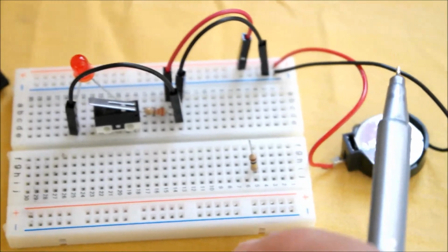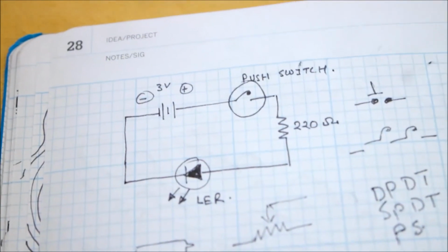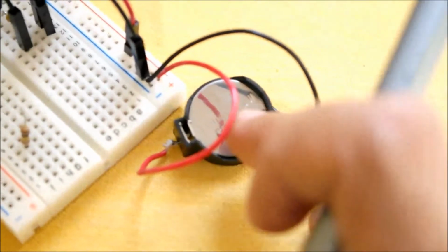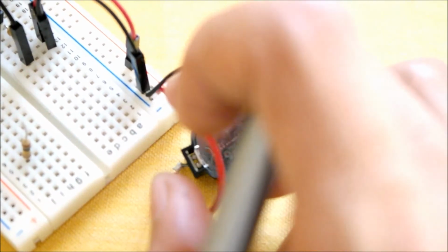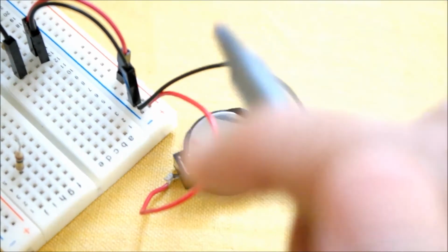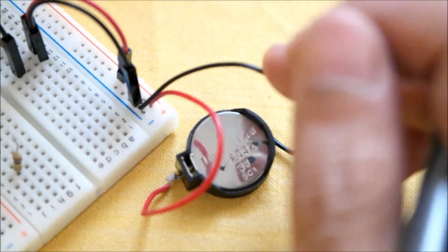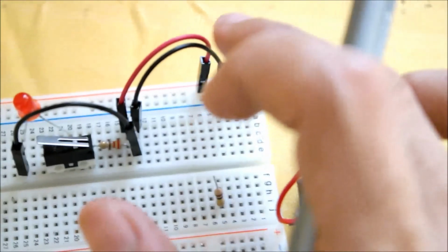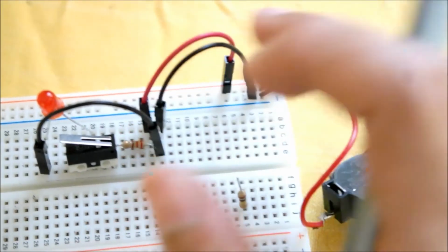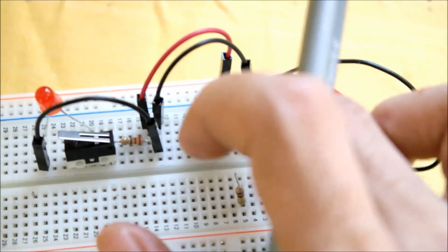Okay, so we have made here the basic schematics, physical version, on this board. You can see we have a coin cell as a power source, and the wires go to the power lines. The positive wire goes to the red line, and the black wire, this is the ground, goes to the blue line here representing negative. I'm using jumper wires to draw this power from these two lines to the main portion of the breadboard. So jumper wires are something like this.